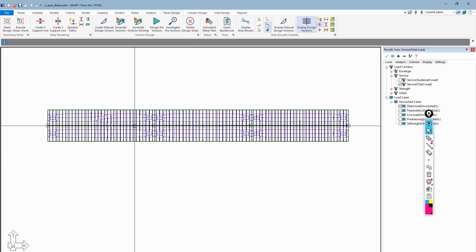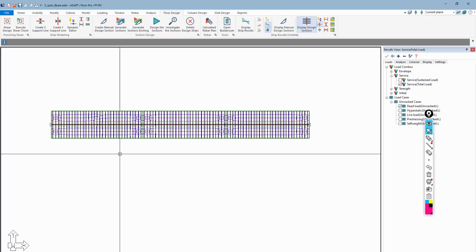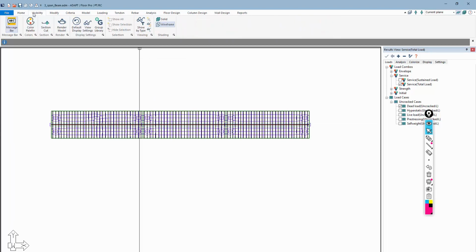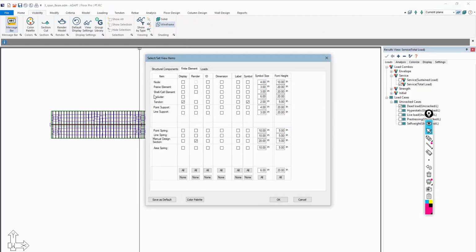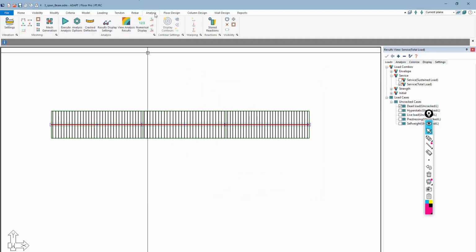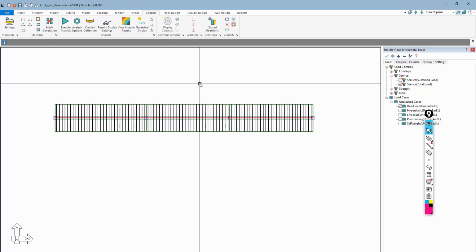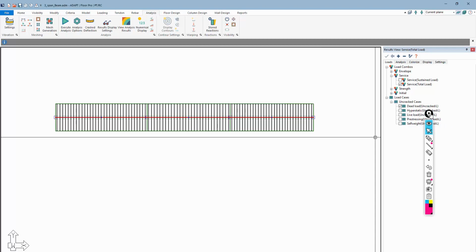Okay, once we've designed the sections, I do not really want to see these mesh shells or elements, so we're going to turn the cells off. I'll go here to visibility, view settings. Under finite element, I can turn off the shell/cell element. I could also do that under analysis, visibility, and turn on this option here. So this is our beam. We're looking at a top view.